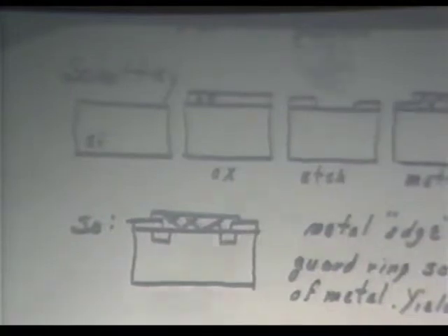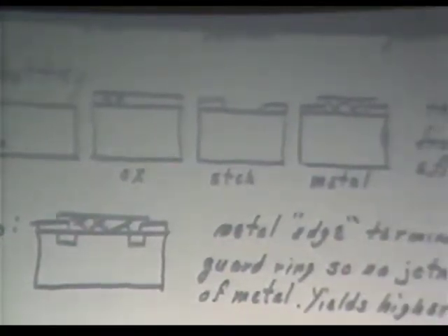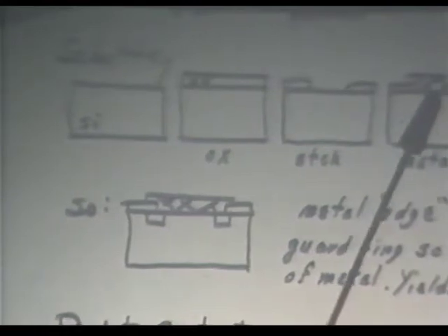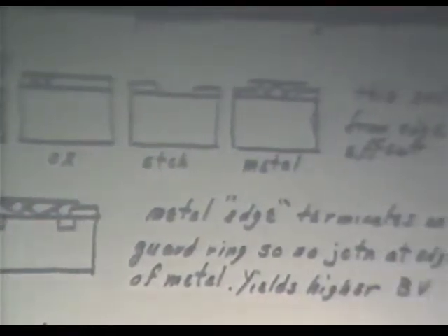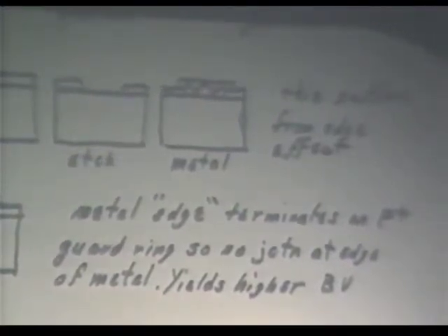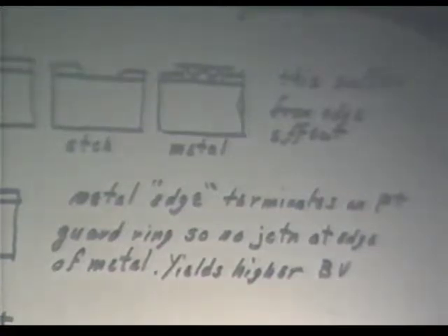oxidize, cut a hole in it, put some metal on it. Now that sounds deceptively simple. I'm sure it's not that simple. But at any rate, the metal silicon interface is where the junction is formed. Now, you hear all kinds of numbers, and it depends on which spec for which device you were looking at as to what that forward's going to be. And it turns out there are several answers that are correct, not for a given device, but as an arm wave on Schottkys, because there are a number of different metals that are used here, or combinations of metals, and they will give different forwards.